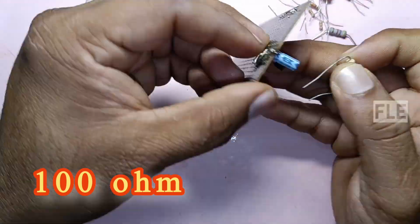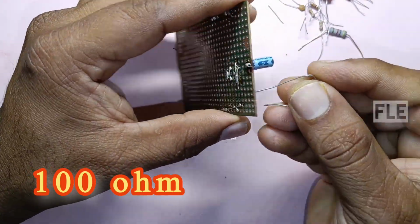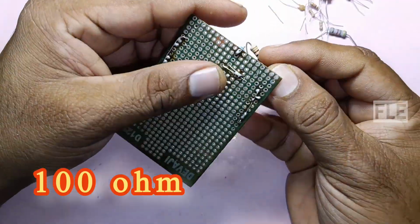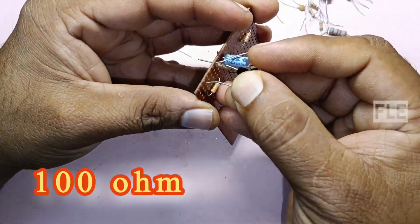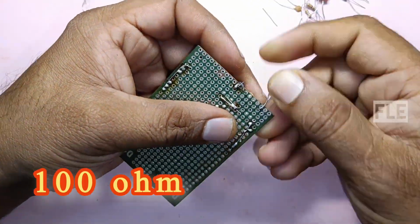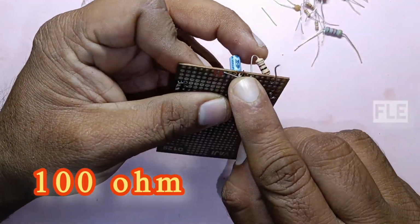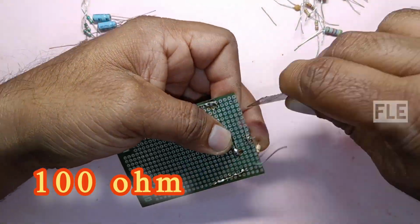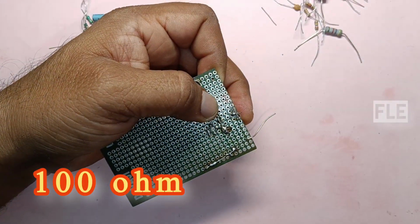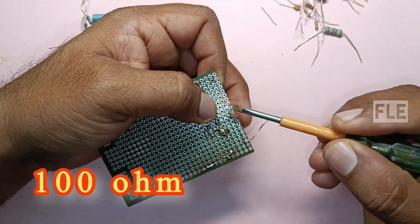Now take the 100 ohm resistor. One end of the 100 ohm resistor is connected to the positive terminal of the 2.2 microfarad capacitor. The second terminal of the 100 ohm resistor is connected to the input terminal. The audio input is given to the circuit board from the 100 ohm resistor.